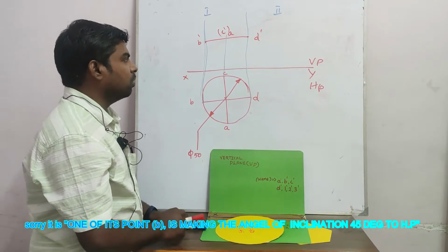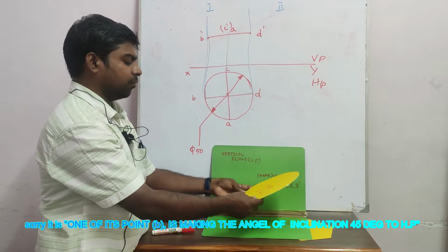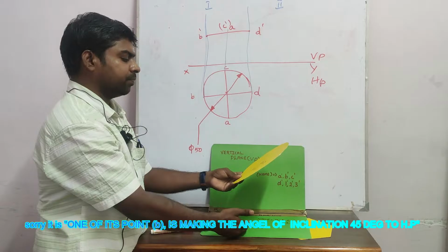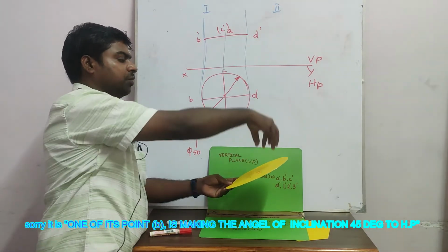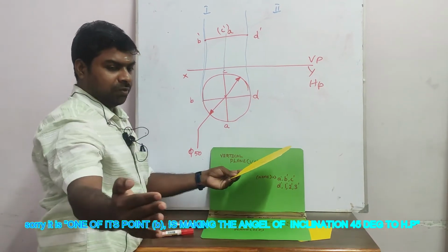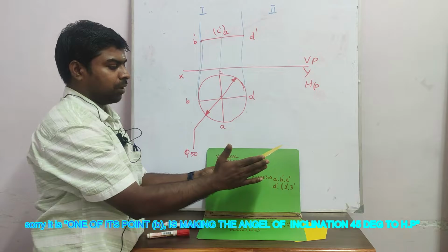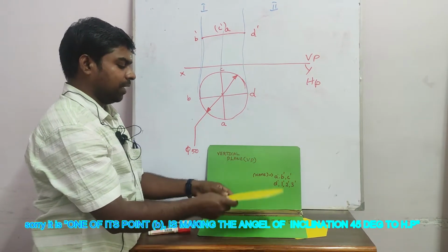Okay. Now stage 2 is the inclinations given by the problem. So here it's 45-degree inclined to the HP plane. Okay, so it is very difficult if you see the object from the top view and reproduce it, but it is very easy if you are seeing it towards the point, in a single line. The projection will be a single line which is 45-degree inclined.